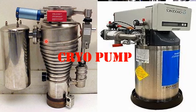So it plays a vital role in decreasing the impurity inside the reaction chamber. Due to this, the cryopump is most common in molecular beam epitaxy, though in combination with the turbomolecular or ion sublimation pump. However, the diffusion pump is not used due to the vapor phase of the oil, which can possibly create impurity in the epitaxial thin film.